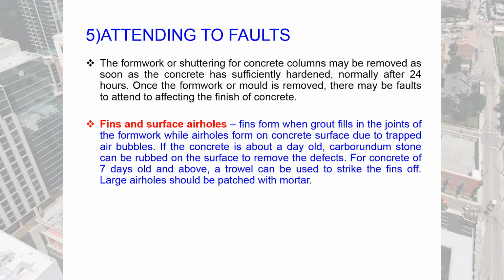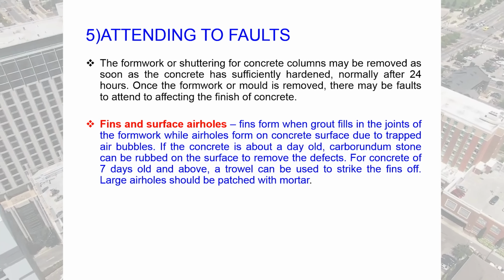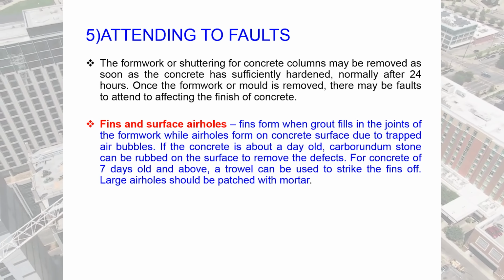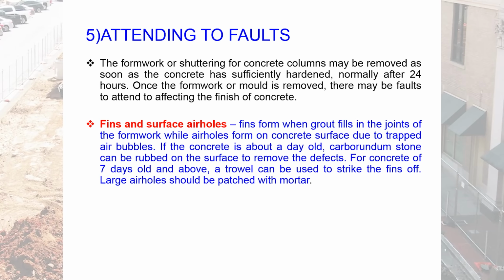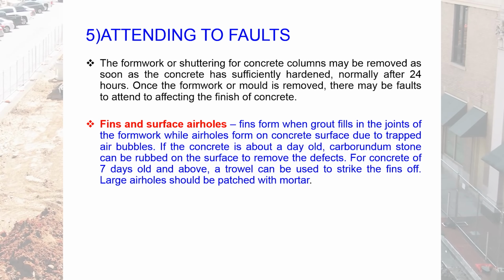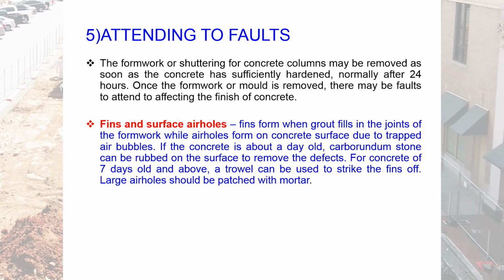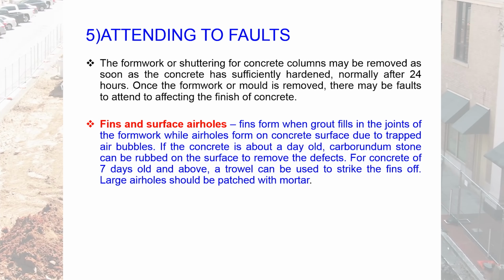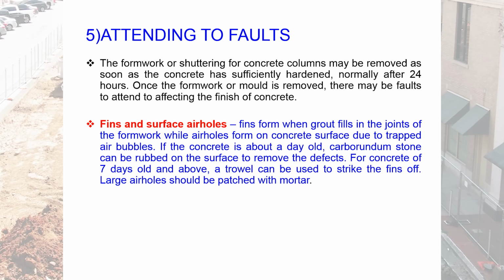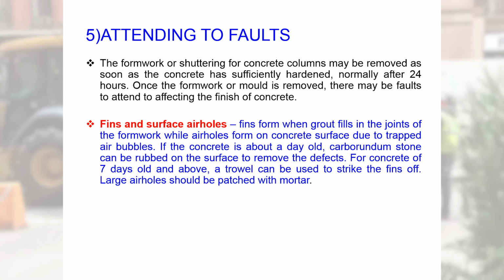Fins and surface air holes. Fins form when grout fills in the joints of the formwork, while air holes form on concrete surface due to trapped air bubbles. If the concrete is about a day old, carborundum stone can be rubbed on the surface to remove the defects. For concrete of 7 days old and above, a trowel can be used to strike the fins off. Large air holes should be patched with mortar.